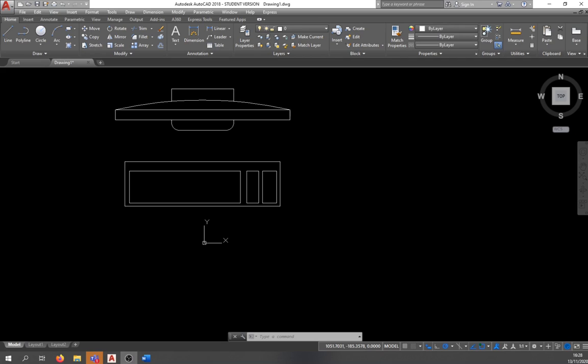So all you have to do is bring up the block command, put in the information, set the point where you're going to move the block from, select the object, so it's all the lines, and that's it really. You can also put in extra information, so usually in a big building you could put in things like serial numbers and the make of the computer, so when someone clicks on a block all that extra information will come up. So again, it helps identify stuff for quantity surveyors, so it's a very, very useful thing.